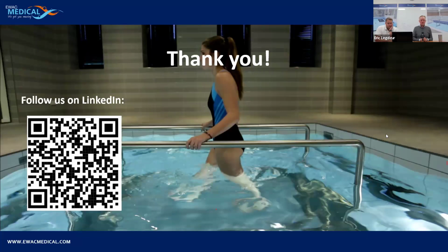Okay, so I see that we are at the end of our questions, if there are any more. Okay, a last one. What is the temperature required in a hydrotherapy pool room? That's a good question, actually. So the air temperature in the hydrotherapy pool room always needs to be a few degrees higher than the pool water itself.